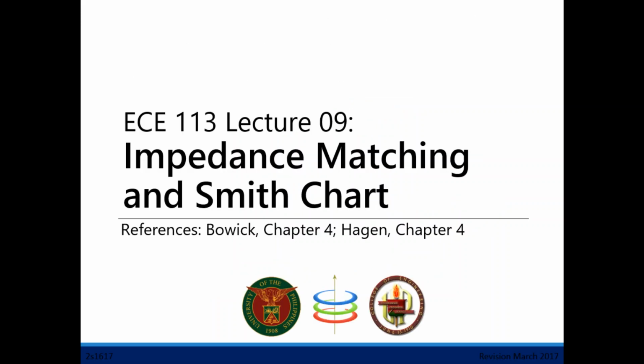And that's the end of lecture 9. Right. Just to summarize, we have two ways to match our circuits, our source and load. You have your L two-element matching network, and you have your pi and T, which are three-element matching networks. Right? So it depends on your application. If you won't bother with the Q of your circuit, use L. If you need to specify a narrow Q, use a pi and T. If you want a wide bandwidth or low Q, use a successive L network, and so on and so forth. So that's the end of this lecture.